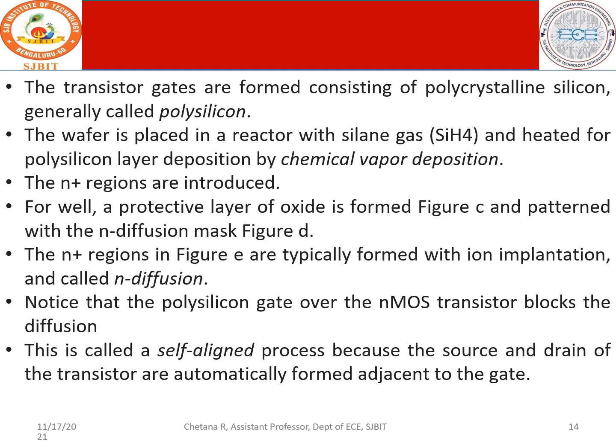Then the N regions are made in the identified regions by a procedure called ion implantation. Either you can use diffusion or ion implantation, and this is called N diffusion. So on your P substrate you are having N type, therefore you are constructing an NMOS transistor. And polysilicon is taken care of. Therefore there is a process which is called self-aligning. What do you mean by that?